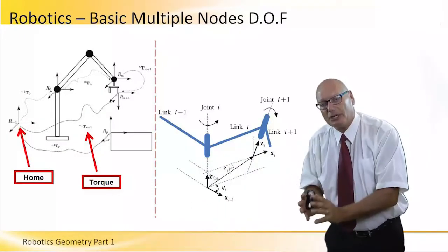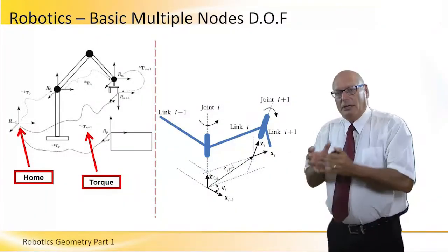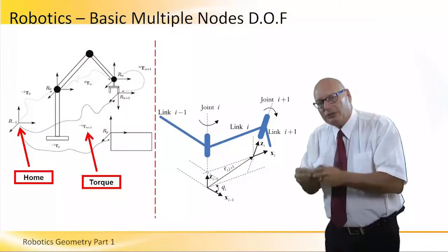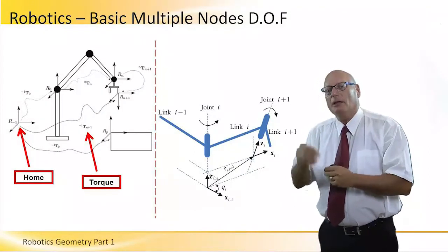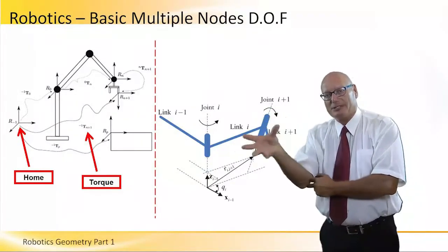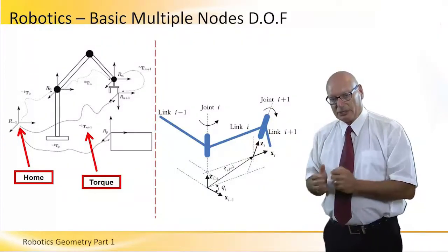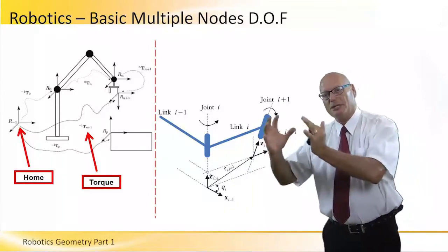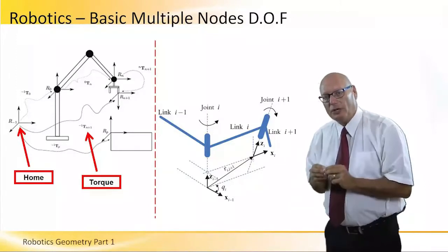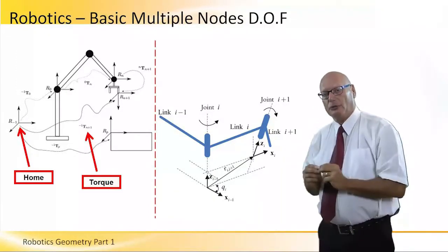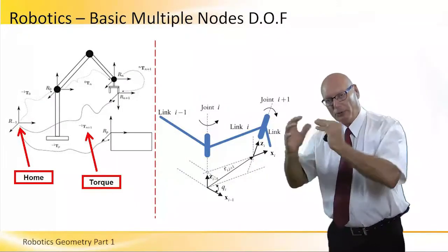Then we have the internal home of the robot, which is in the base. No matter where the robot is, that home, this personal home of the robot, remains the same, and from which all the joints are calculated. The position in space of all the joints is calculated. So the external home is to know exactly where the robot is within its environment, and the internal home is to know where each joint of the robot is within the robot working space, operating space.